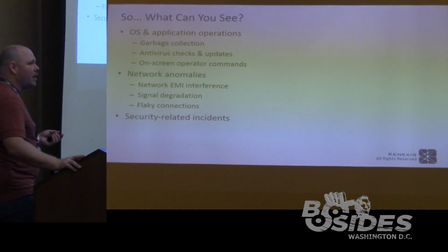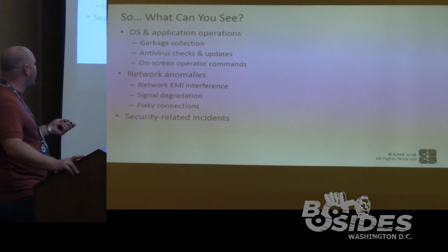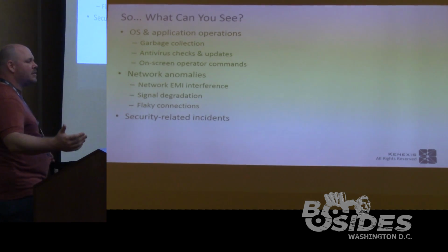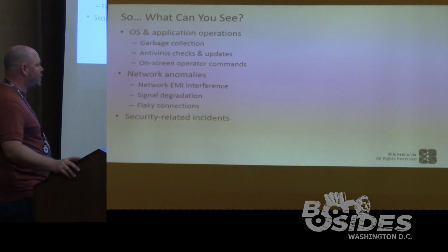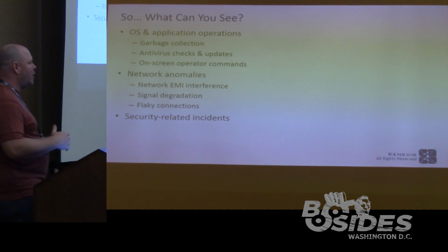There are network anomalies. A lot of times in these plants, you've got large-scale EMI interference. Large motors about the size of this room generating a lot of EMI, or welders, or toxic chemical areas where it actually corrodes the contacts.